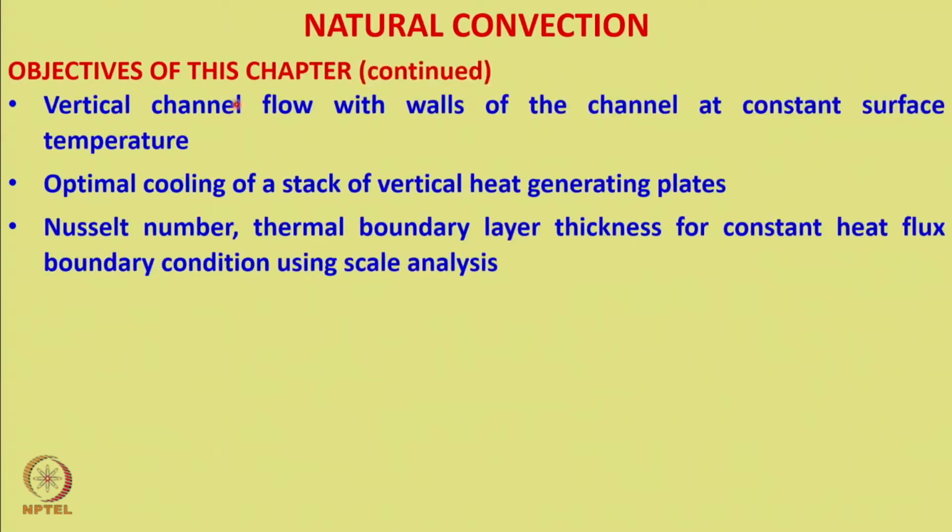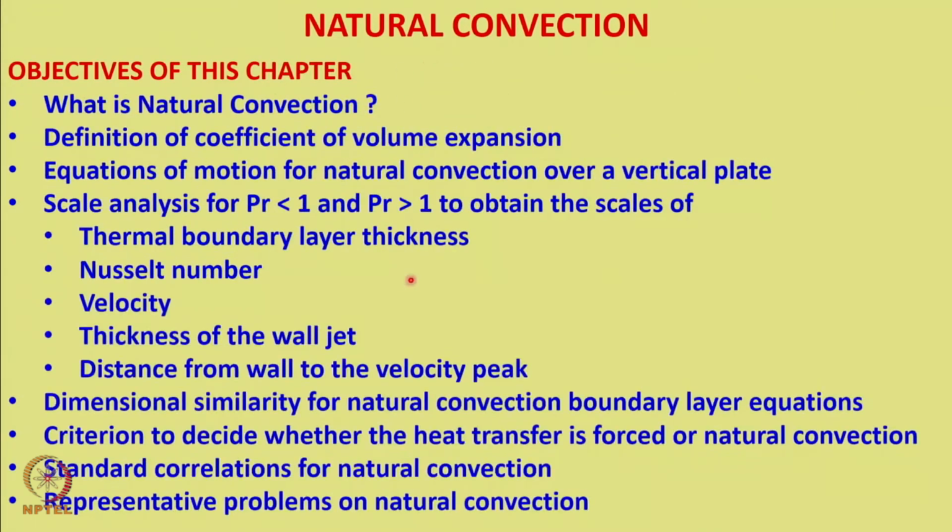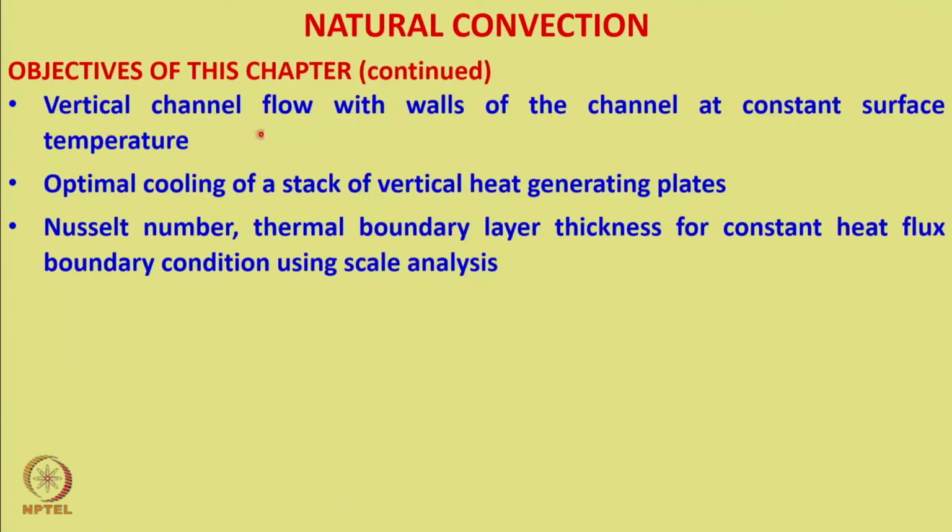And then the interesting thing: with all these basics, how can I apply them to real life? That is vertical channel flow with walls of a channel at constant surface temperature, where the channel flow is occurring because of natural convection only, and optimal cooling of a stack of vertical heat generating plates. That is, if you want to stack the circuit boards in your computer, how do you stack them, how close should they be so that the cooling is effective? That can come from these fundamentals.